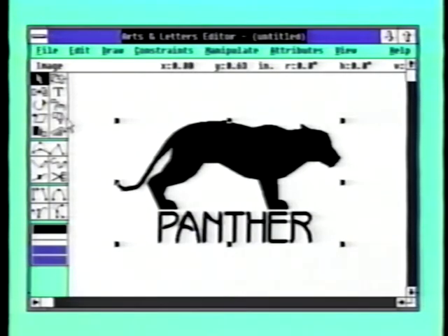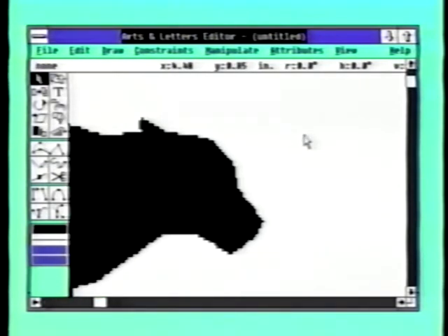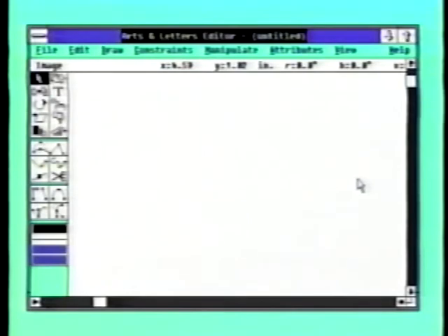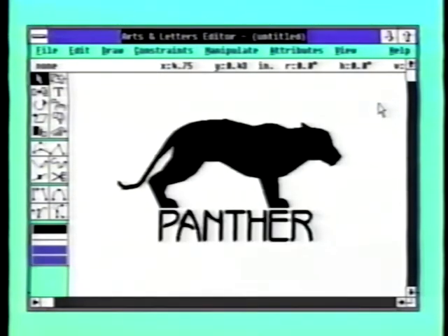Let's use the graphics editor zoom tool from the toolbox to take a closer look at this TIFF image. You will notice that it has a rough stair-step appearance. As you can see, the bitmap doesn't retain the underlying curve information of the natural object. With the Auto Trace tool, you can convert this scanned image to a Bezier curve-based object. Simply select the Auto Trace tool and click on the area of the TIFF image that you want to trace.